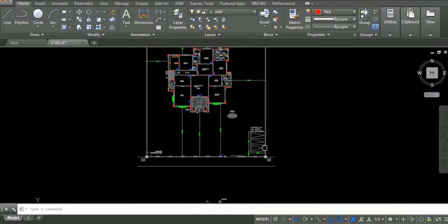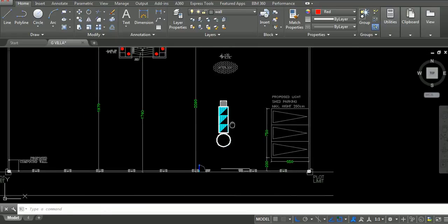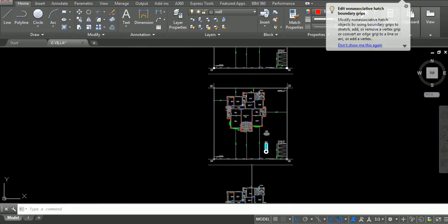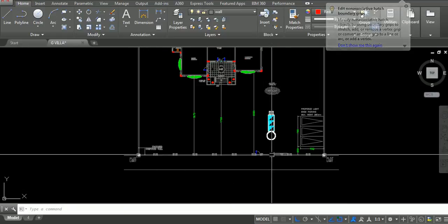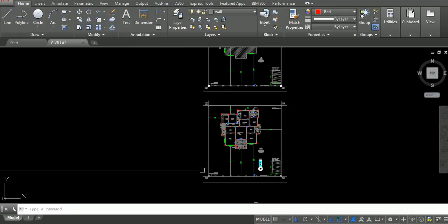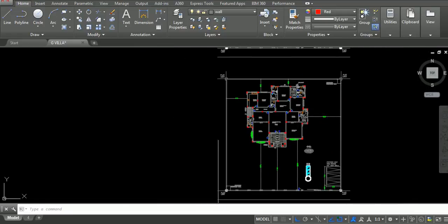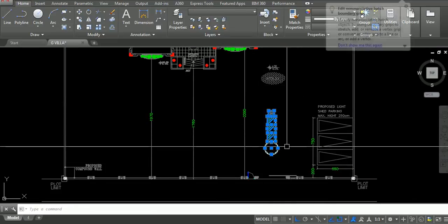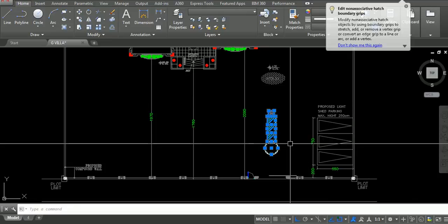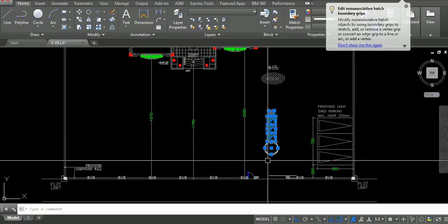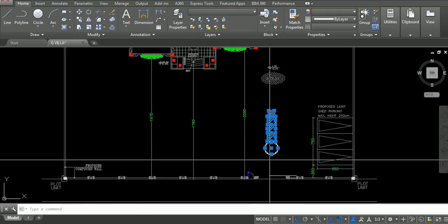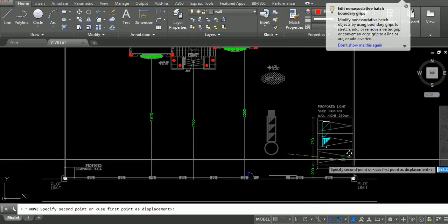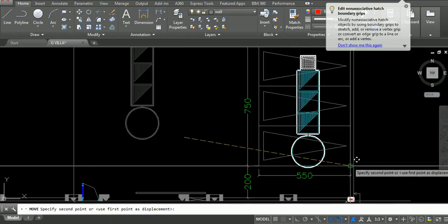Okay, the first step will be choosing where to place our septic tank. The septic tank usually should be near the road, and in this case our road is here, and these are the neighbor compound walls. Here there is one neighbor. So it's always preferable to be near the road, of course, for the future connection with the government. But where to put it? We can put it wherever we want in all these areas. But I always prefer to put it under the parking shed.